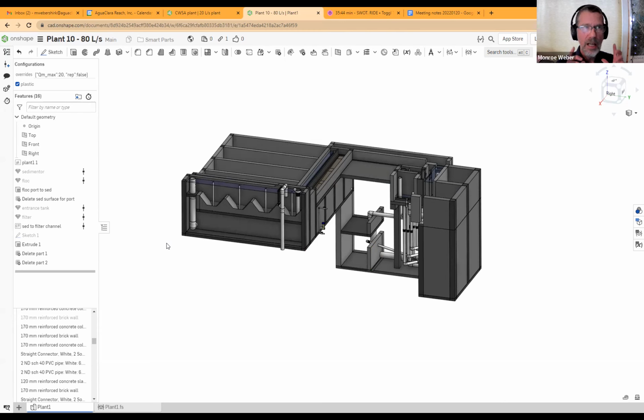So you will be, for example, determining the dimensions of a tank by figuring out what the volume needs to be and what the dimensions need to be. And then once you know the dimensions, you will use a feature that draws a tank, and you will set the dimensions in that feature using the dimensions that you've calculated using variables. Did I answer that? Yeah, thanks.